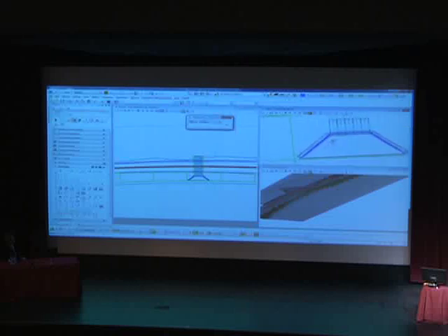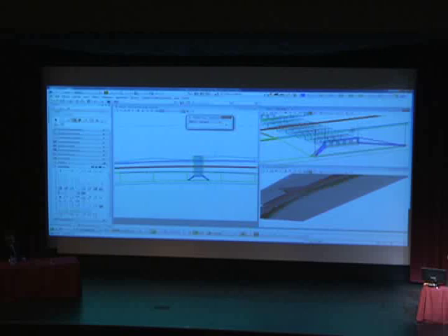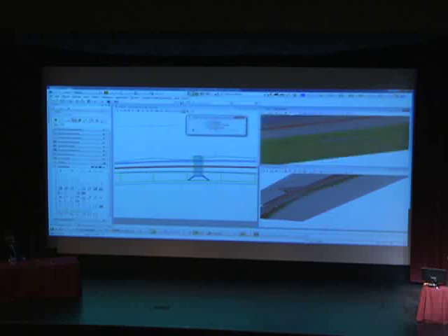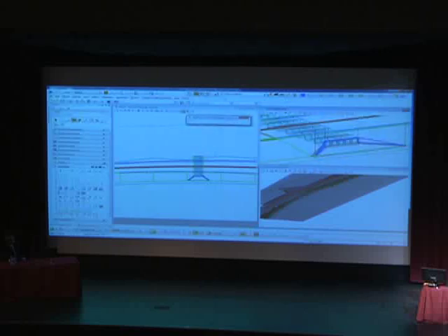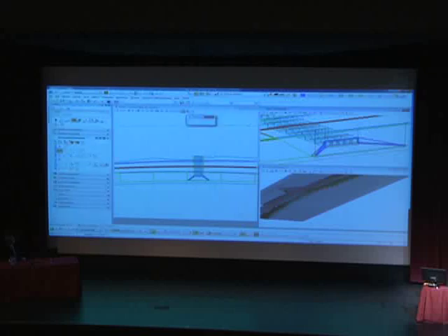So next, my template is still tying into the existing grade ditch bottom feature definition. What I need to do is switch that to tie into the back of head wall. To do that, I'm going to have to create another alignment around the top of that head wall and give that a profile. Now, it sounds a little tedious, but it's not that bad.